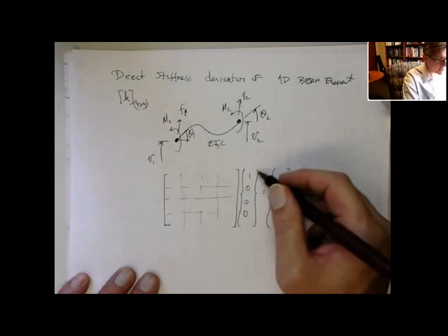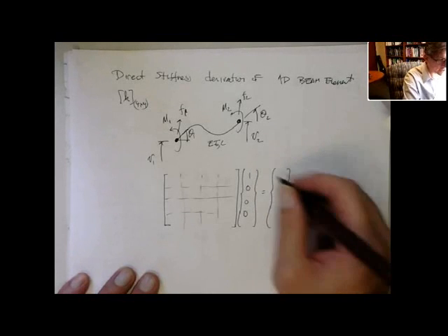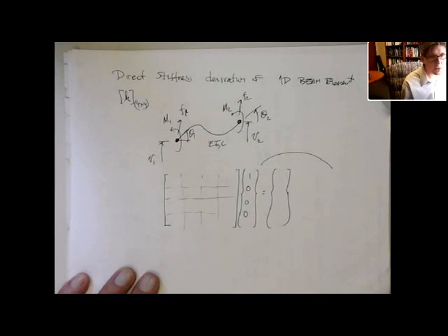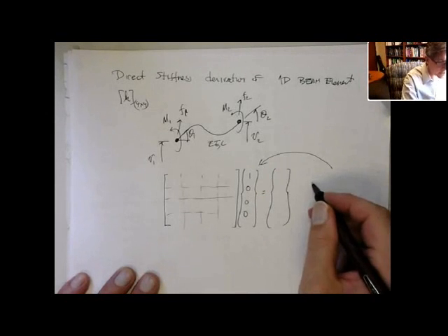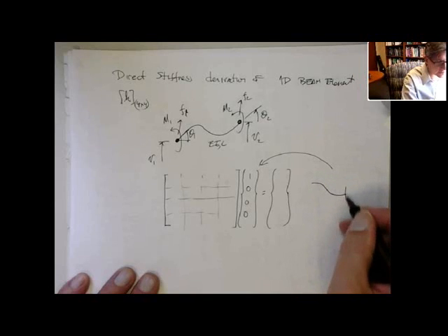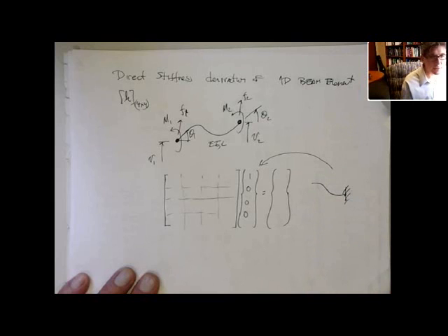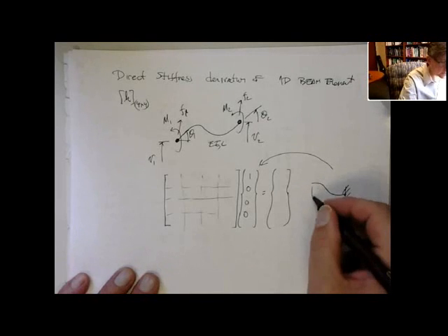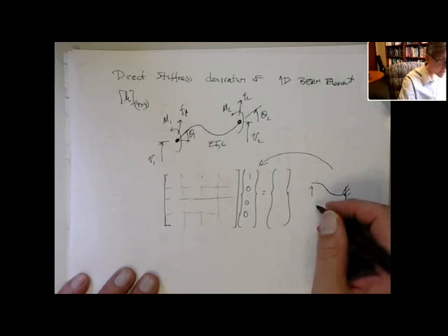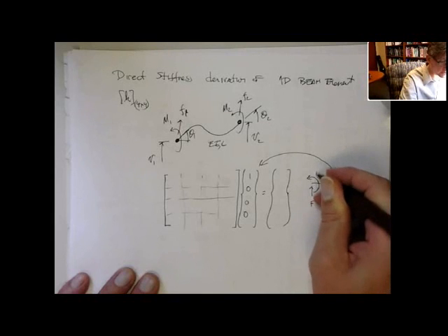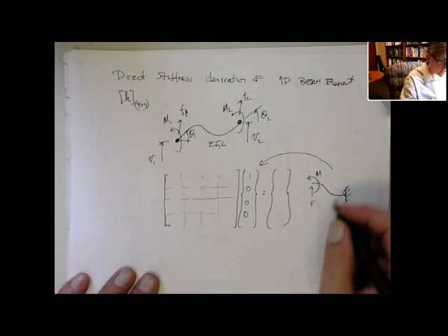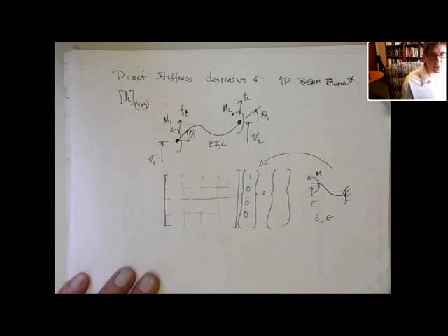so that this is basically saying, if you look at this type of mode, everything is 0. Theta 1, V2, and theta 2 are all 0. The only thing that's happening is it's deflecting up 1 at node 1. So actually that beam basically looks something like this. It's that type of deflection pattern. And we can actually figure out using basic beam equations what is the force and moment, and from that, you can get the deflection and the rotation at those points.